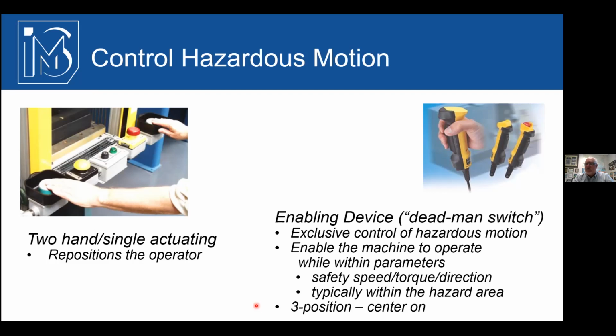As long as somebody's squeezing it, it meant that you could still run. So it was a 2-position, and the person squeezing it puts it in the safe position too. But what was found was that when people get injured, they didn't necessarily open their hand, they clenched it tight. So the 3rd position was added. So with a pod, the center would be the enabling position. If somebody got hurt, they could either squeeze it or drop it, and that would put it basically into a safe state.